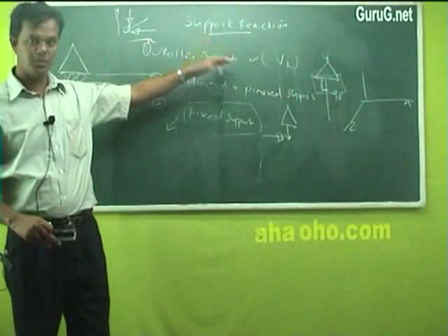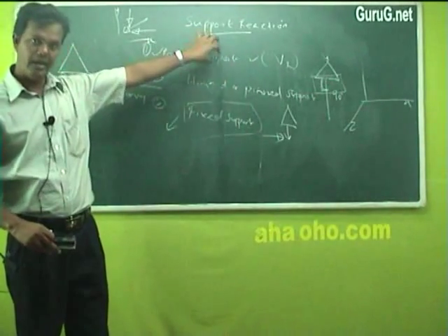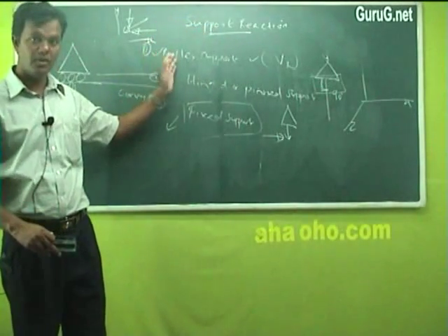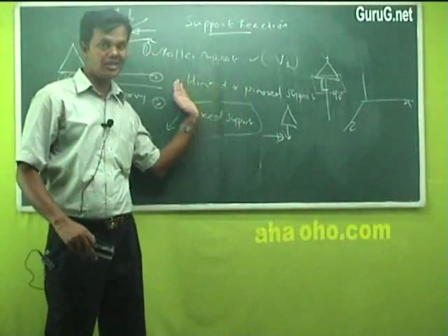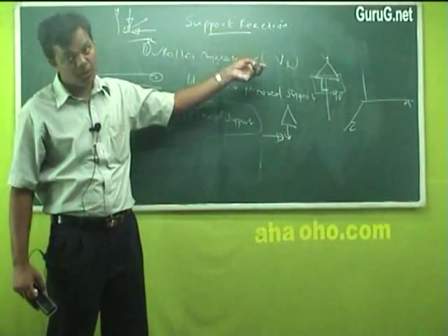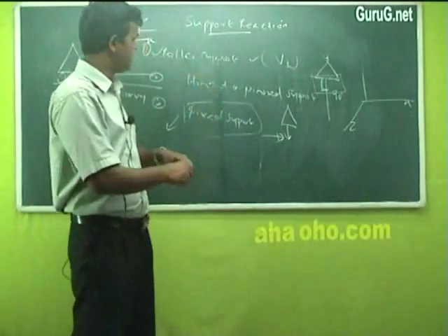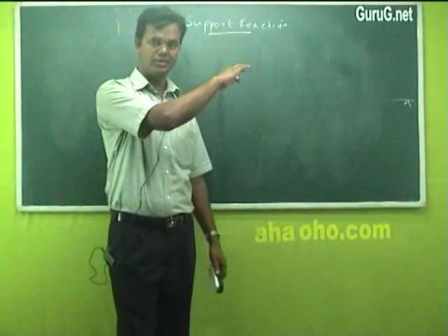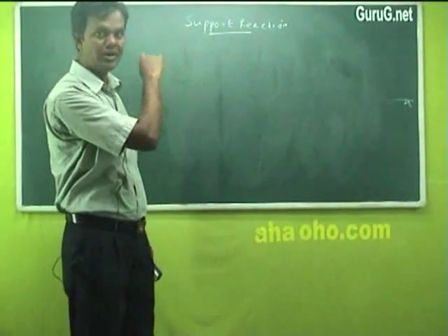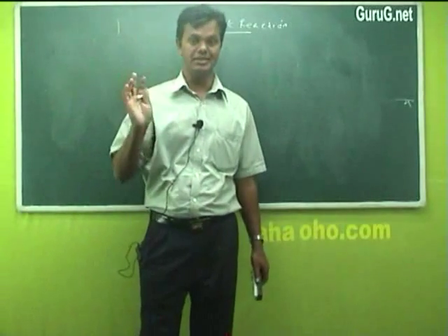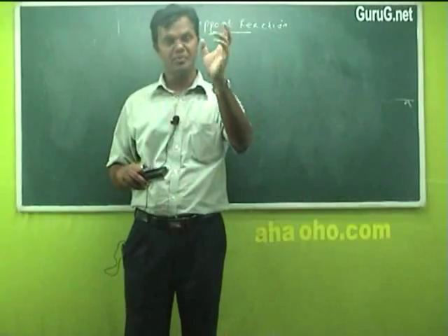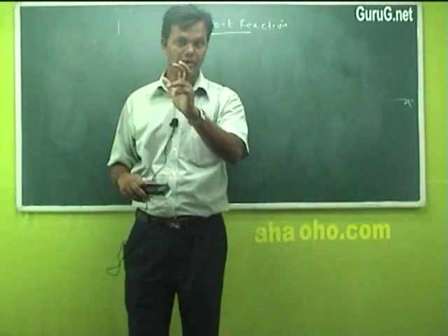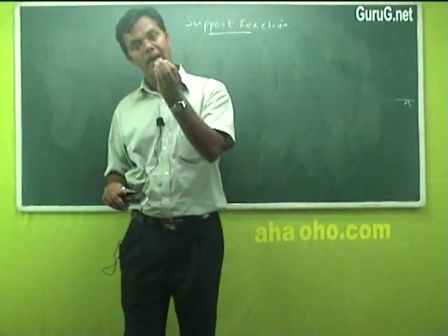So the support reactions are what we have to understand, analyze and study, because any body subjected to some kind of load will have to come to equilibrium only by understanding its horizontal and vertical reactions as well as the rotational load also, right? So that is the idea of studying your support reactions. Under the support reactions, you will have to learn one or two problems to understand how the moment gets changed. Moment is nothing but, I told you, force into perpendicular distance. I repeat again, it is force into perpendicular distance, not merely a distance at all, because the moment is applicable in either of the body.